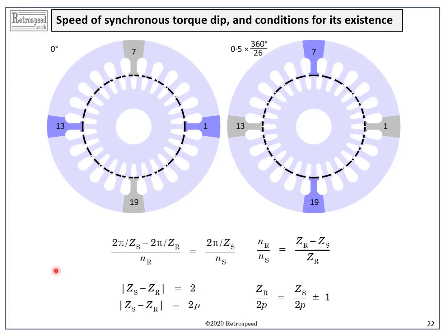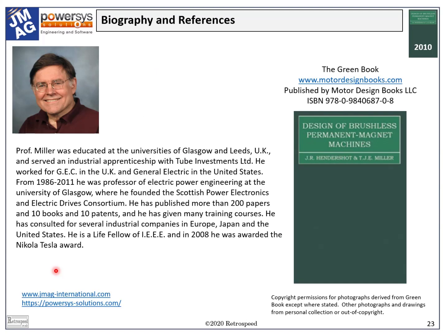Time harmonics. Aren't all harmonics time harmonics? Absolutely not. All the harmonics we've been talking about here are spatial harmonics. We have tacitly assumed that the voltage and current are sinusoidal functions of time, with no harmonics, and we still get the parasitic torques. If on top of that we have time harmonics in the current waveform, it becomes still more complicated. If you would like to see a table of some of the interacting space and time harmonics, you can find them in the Green Book, Chapter 12.